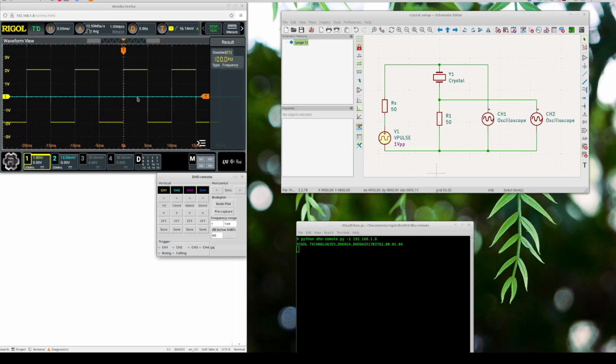There's nothing special with that, and channel 2 seems to have nothing on there. So this is channel 2, this is channel 1. Channel 1 has a square wave signal, and I put it on 500 millivolt, and it is just barely hitting the maximum output. So that's what I want.